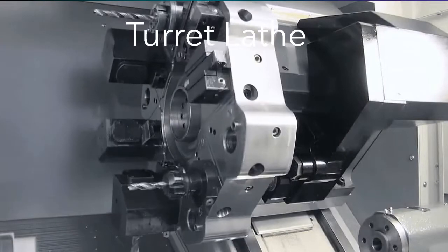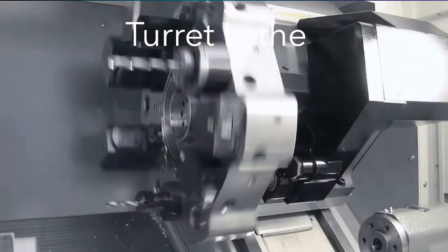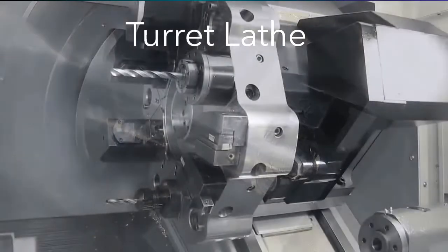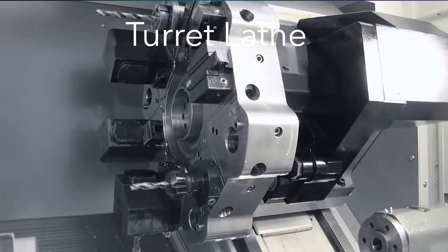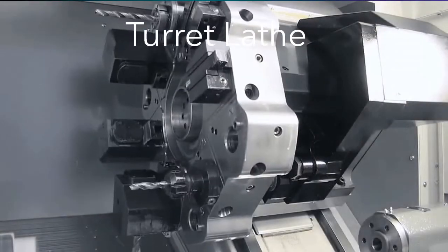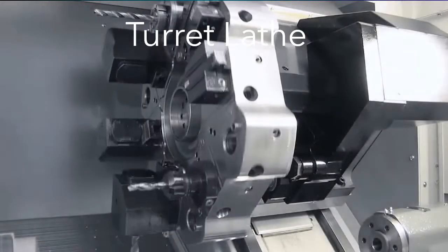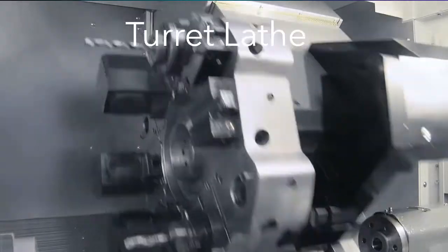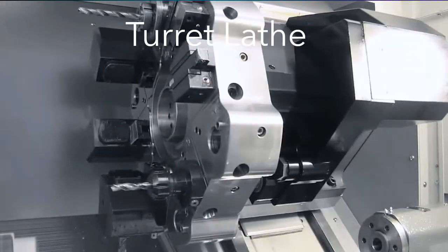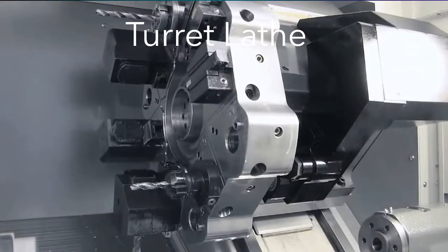A third lathe is a manually operated lathe in which the tailstock is replaced by a turret that holds up to six cutting tools. These tools can be rapidly brought into action against the work one by one by indexing the turret. In addition, the conventional tool post of an engine lathe is replaced by a four-sided turret that is capable of indexing up to four tools into position.